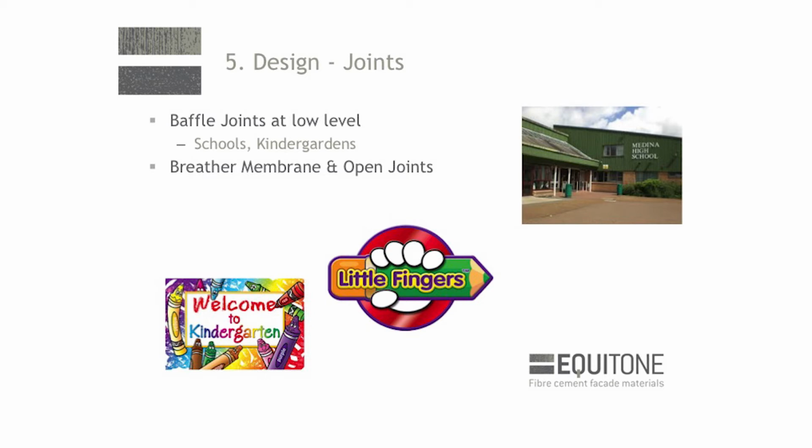Kindergartens, I think it's for small children. It's an invitation if there's a gap between two panels for little fingers to go in and little fingers not to come out again. On older schools, there's a tendency for cigarettes to go in and cause all sorts of problems in the future if one catches fire inside in the cavity space. One thing to bear in mind is open joints and the use of membranes or insulations or breather membranes in the cavity space behind.